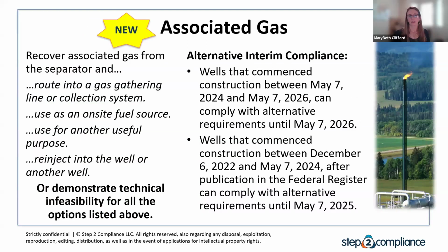And then also another new aspect in Quad OB is associated gas from oil wells. And really they outline 4 key ways that they want you to be recovering that. You can either route it to a gas gathering line or collection system, use it as an on-site fuel source, use it for another useful purpose, or re-inject into the well or another well.